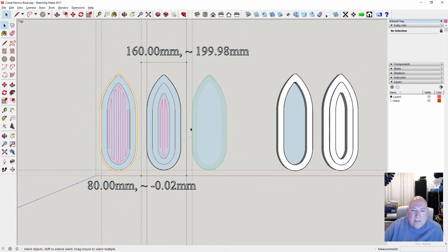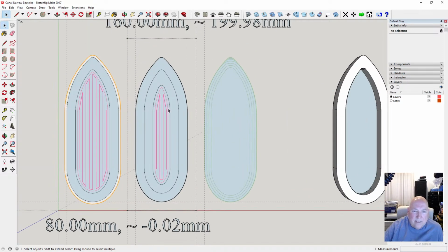Okay, so we can mill out that. So first we're going to pocket there the outside, then we're going to, these are the wrong way around actually, we need to move these around, don't matter. So we'll do that first, and then we'll do that and then cut it out. So we're going to pocket that, so then we're ready to cut it once we've pocketed that. So let's put the outside cut on it. Okay, we're done. Save. Let's output the G code for that bit.